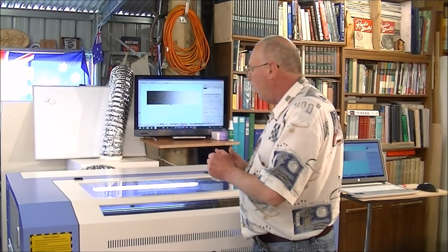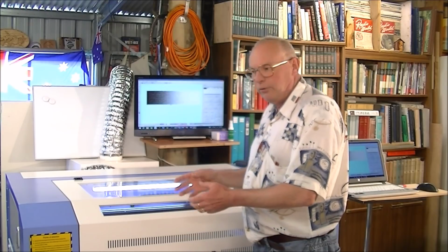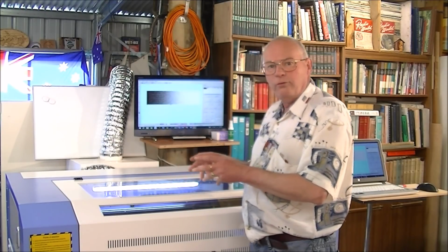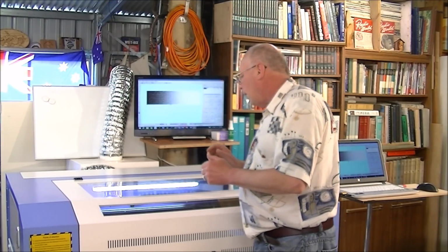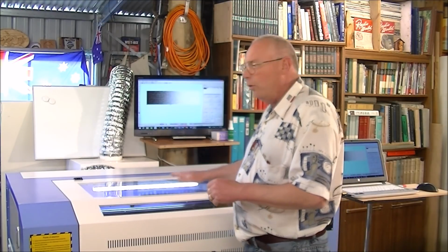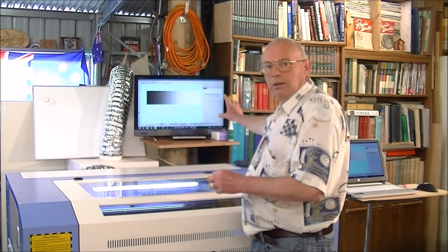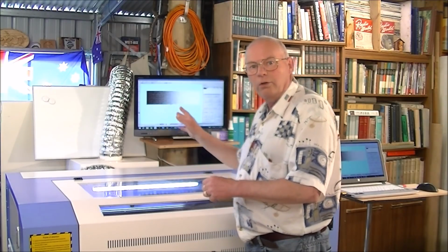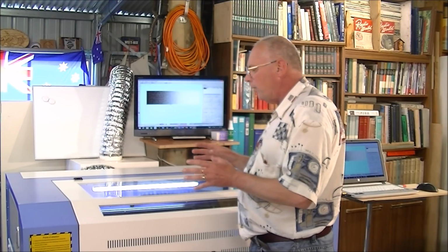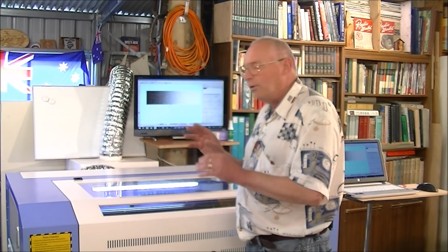Yesterday, in the last video, we found out the minimum that the laser would fire at, which was 10%. And the maximum we know on the scale within LaserCut is 85%, which relates to 100 watts. So what we are going to do today is find out the parameters that we can use with this laser for dithering a picture or a photograph.